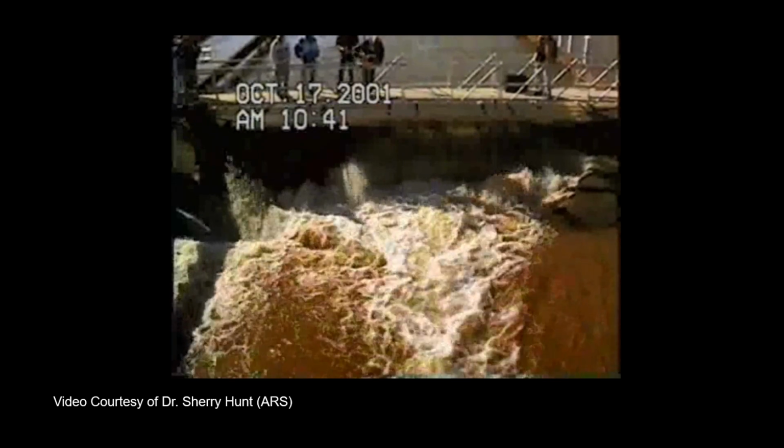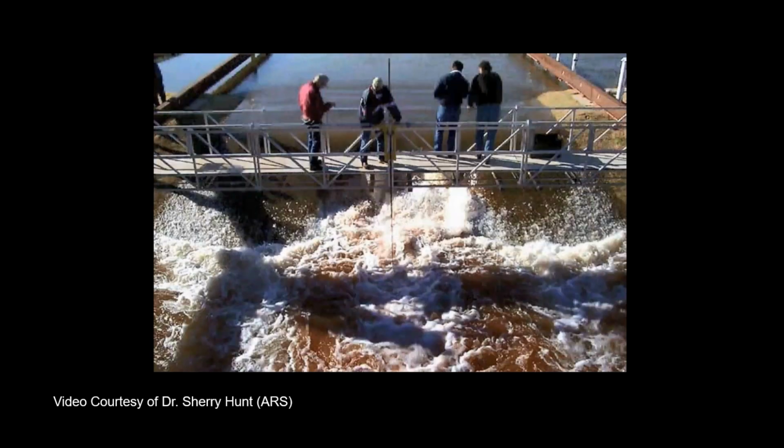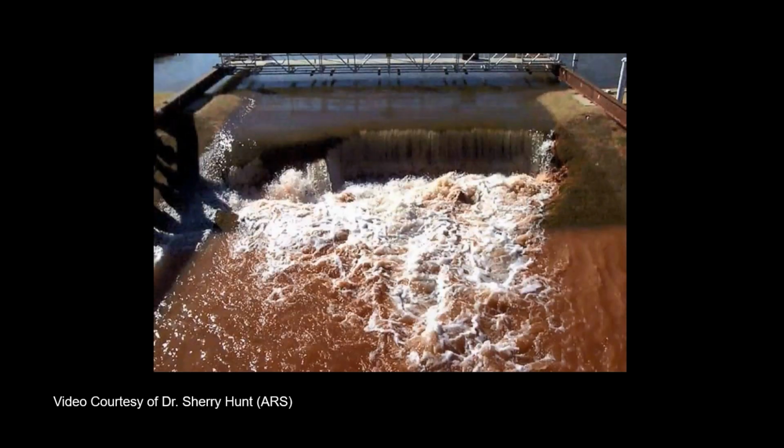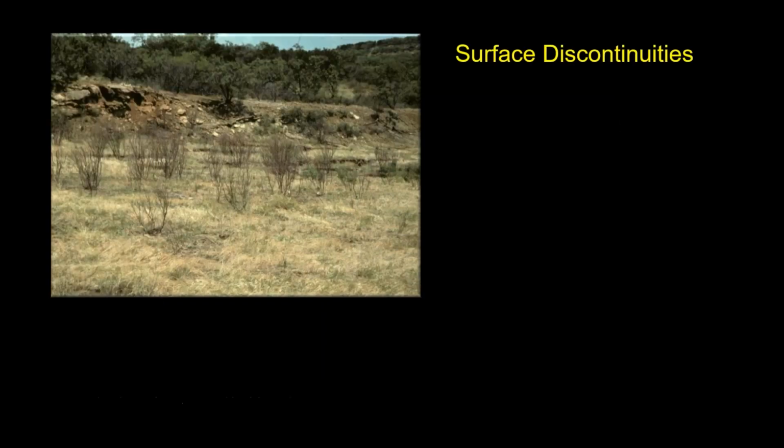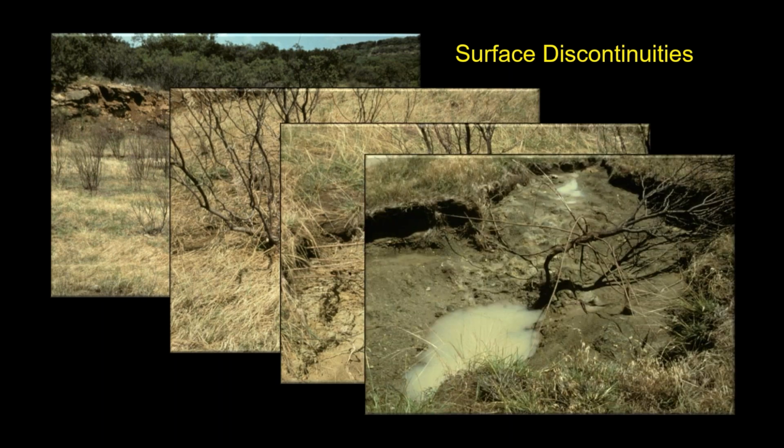The next slide I'm going to show you is the exact same video, but very quickly, so you'll be able to see it more effectively. So that grass lining is very important for a spillway. Also, not just tire tracks, but even something as simple as allowing woody vegetation to grow in the spillway. If you stop mowing it and you allow a different kind of vegetation to take over, that will cause flow concentrations and can result in initiation of erosion in the spillway and premature failure of the spillway.